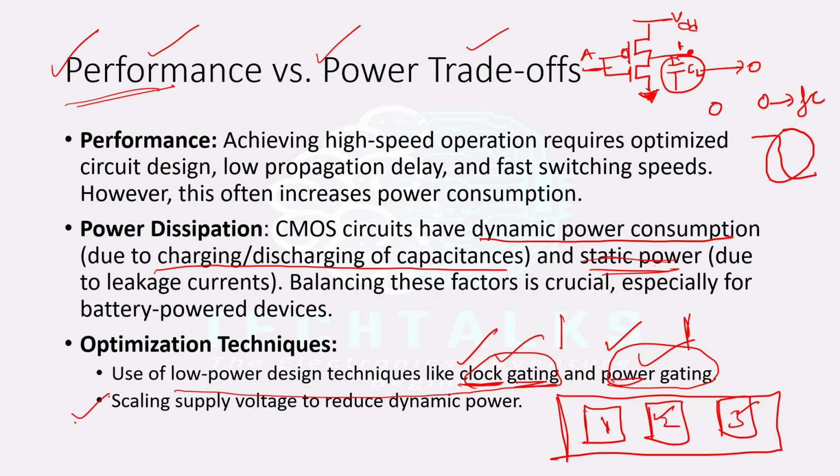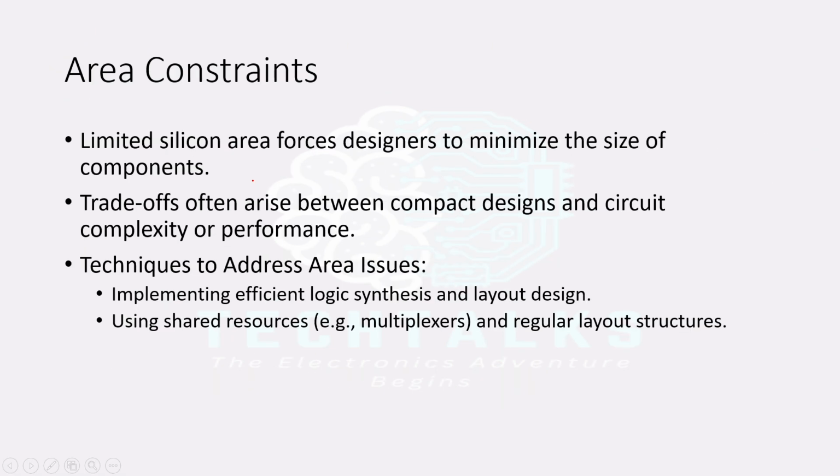And the next thing is, for optimizing techniques, we'll scale the supply voltage. Scaling supply voltage is nothing but moving through or navigating through technology nodes. For example, 180 nanometer, 90 nanometer, 45 nanometer, 22 nanometer. As you move down, you can scale down voltages, because for very little voltage, the electric field is good enough to form the inversion layer for conduction, or the minimal voltage will give you good control on the gate region. So scaling down voltages also will reduce the power consumption.